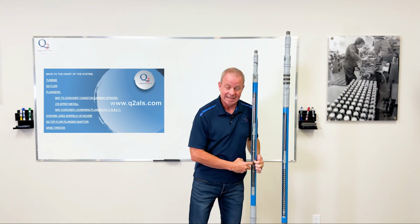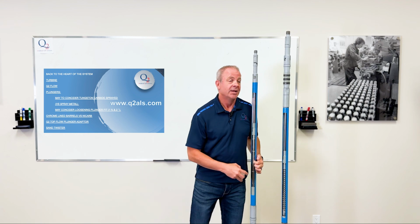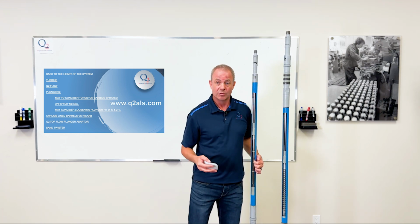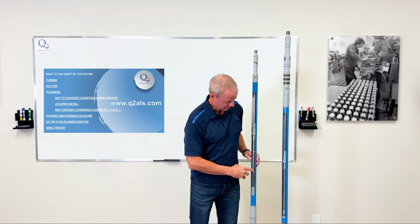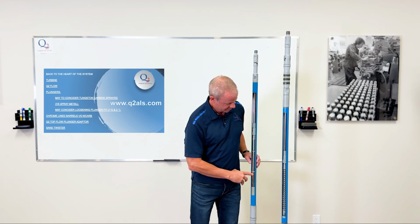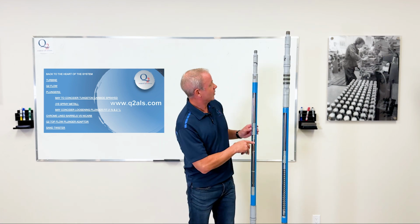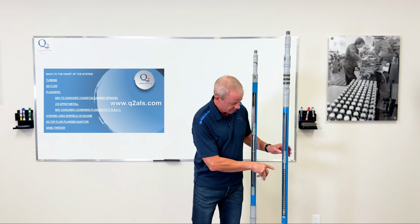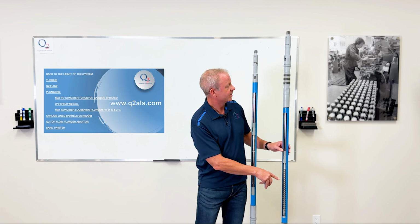Because this could be a really nice tight fit. This can be anywhere between a 2 thou fit and a 12 thou fit. Normally they're around 8 thou if you have some solids in there a little bit deeper. And you can see on this particular one, this is a smaller pump size. I think it's 1.5 inches, and this must be 1.75 inches, I think, with a 2-inch standing.